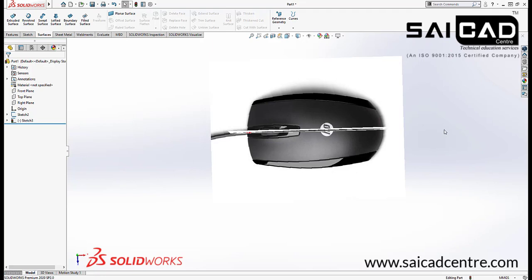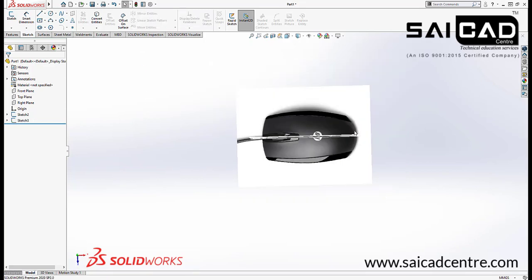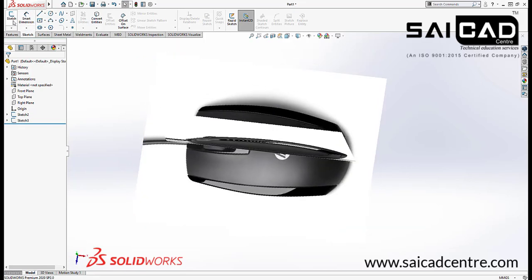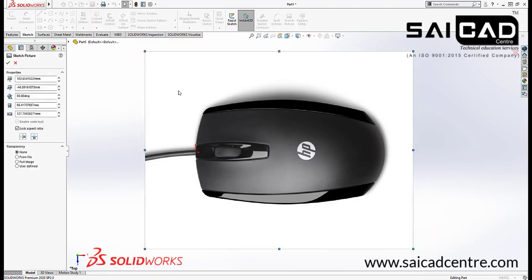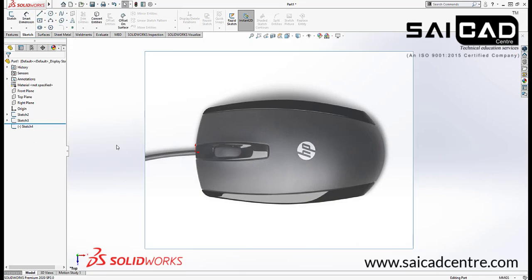So now just create the sketch. I'm going to exit out first. You can see this one has some symbol here. This is for the rebuild. You can press Ctrl B also, and the symbol will be removed. So now just select a sketch or select a plane first, go to the sketch, and you can just draw here right now. If you want to fade this, you can just double click and use the transparency from here, full image. I want to fade it around somewhere here, so you can just fade it.